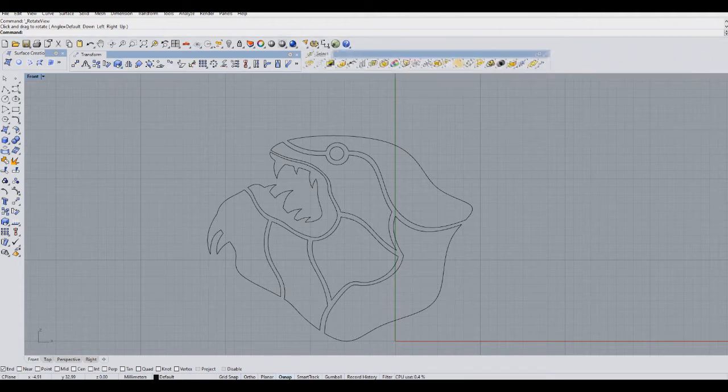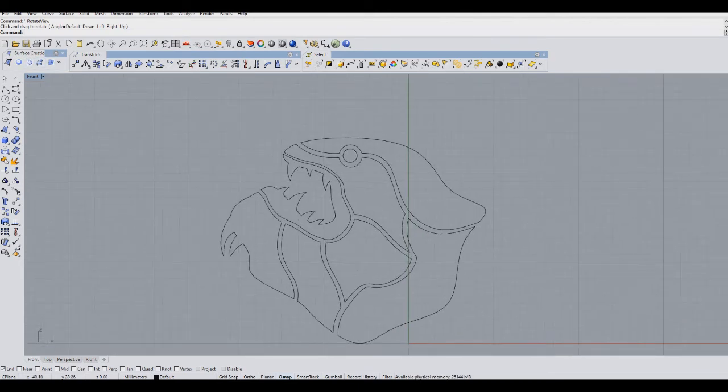So what I ended up doing was setting up floating toolbars, which you have the ability to do in the program itself. Rather than make a series of toolbars that would take up half the screen, I pulled out the ones I needed, and I have them floating here, overlaid below the command line up here. Because pretty much all the stuff I do uses two-dimensional commands and some surface commands, creating these as floating objects was good enough, and it ended up being fine for the UI the way I use it.